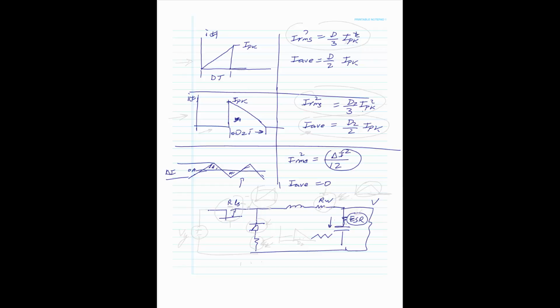What is the power dissipated here? Well, we need to go back to what the waveform looks like. And even if we're in discontinuous conduction mode, the beauty is I can do discontinuous conduction mode, not a problem. What does it look like discontinuous? It looks like up, down, flat. That's one of the waveforms that we had previously.